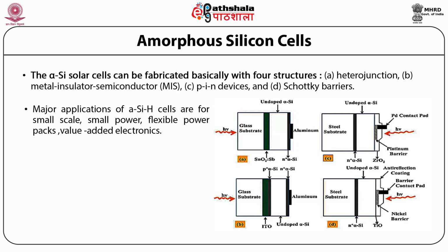This Schottky solar cell structure has many advantages over other structures. Both the barrier height and the field region width can be improved by introducing an insulating layer in the Schottky barrier and using lower work function metals which are less expensive than platinum or palladium.